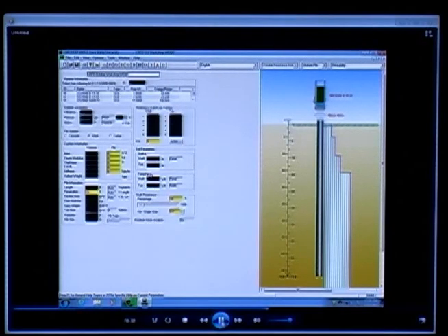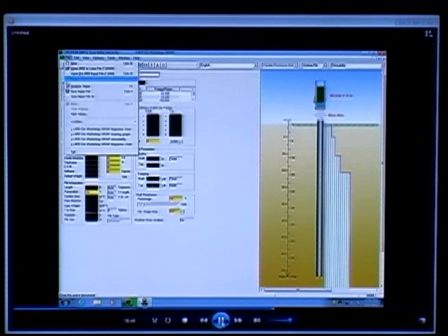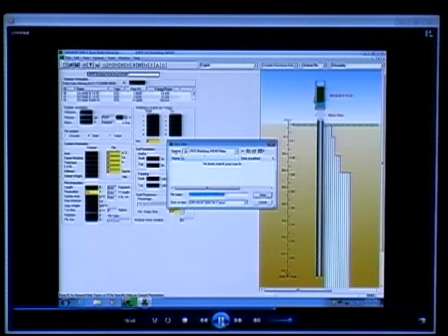Although the drivability analysis does not require these soil parameters, they are required in the bearing graph analysis that is described later. Save your drivability file, select File, and click on Save Input File As. Go to the directory and type in your file name.